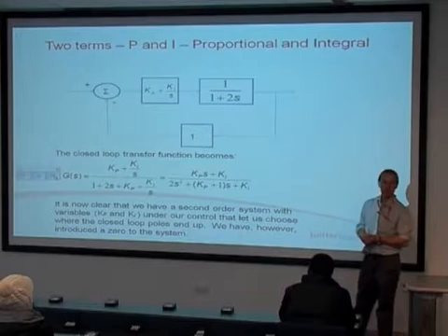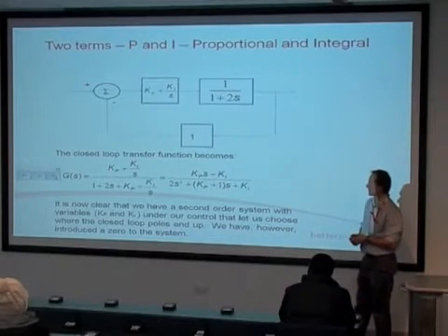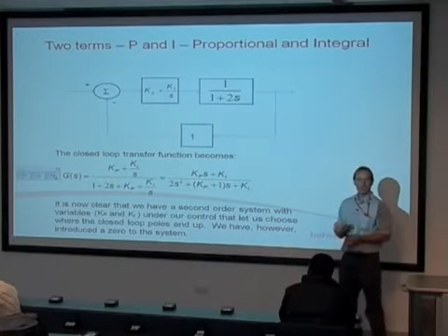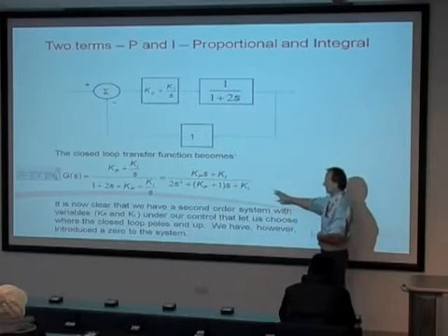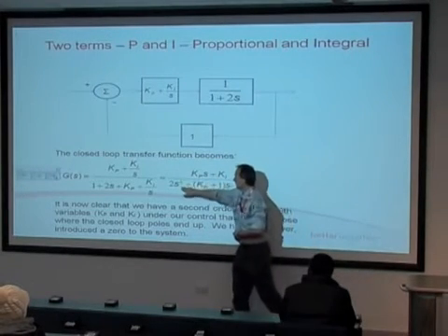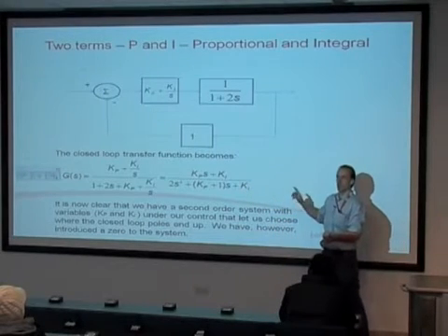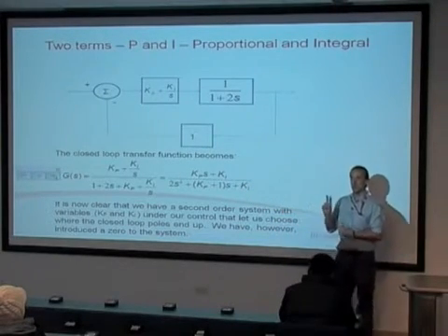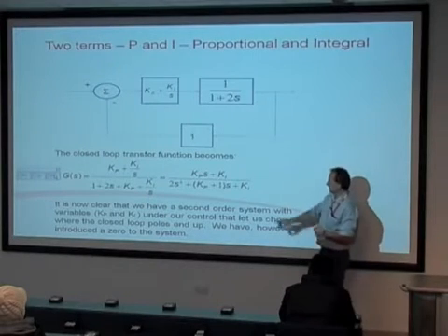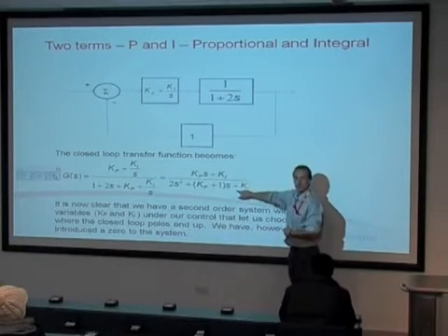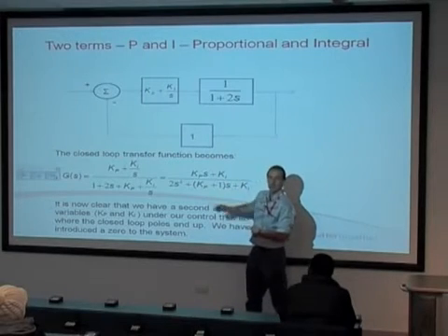It's come out second order because of the integrator term. Looking at the denominator particularly, I've got a second order dynamic where I've got control over 2 variables. I can change Ki, and I can also change Kp.